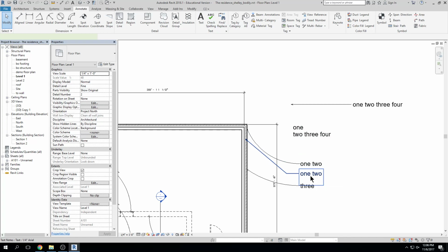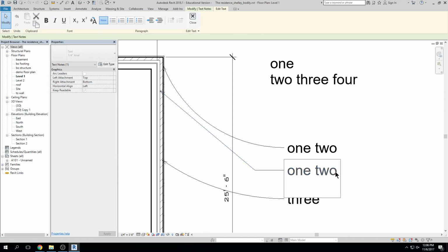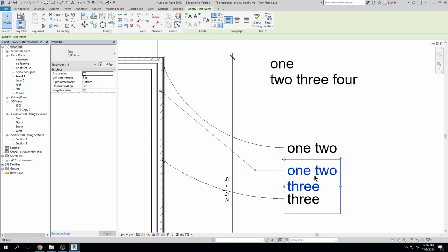Okay. So we have text, we have leaders. If I click on my leader, let me do a couple of strings of text. Close. Okay. And I click on it, you'll notice that I have these little add leader buttons here. AutoCAD did add these several years ago, but if I want to create a new leader, I would click, place a new one, click, place a new one, and I can place as many leaders as I'd like, on both sides. And I could get rid of a leader, and it gets rid of them from the newest one created. I can change my justification.